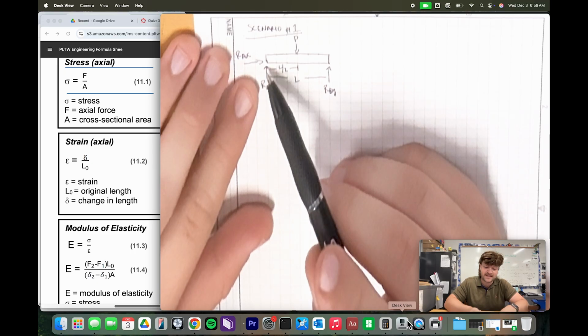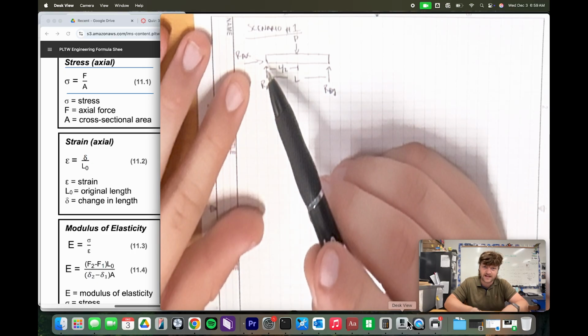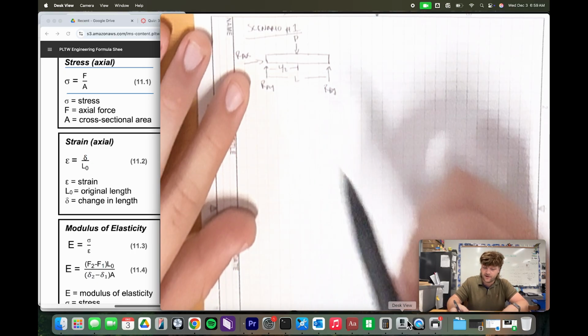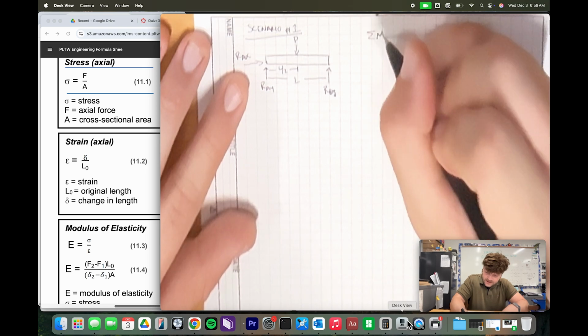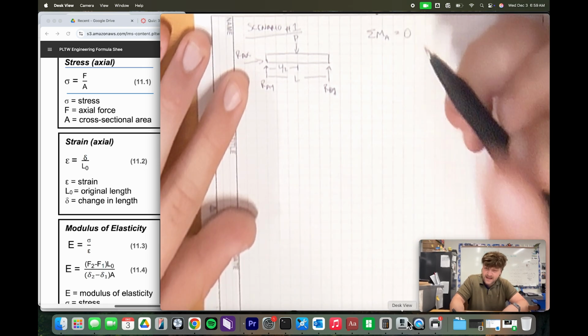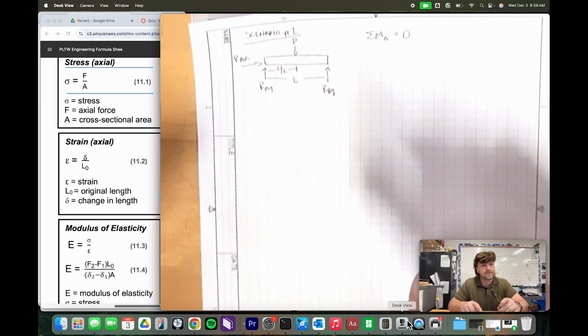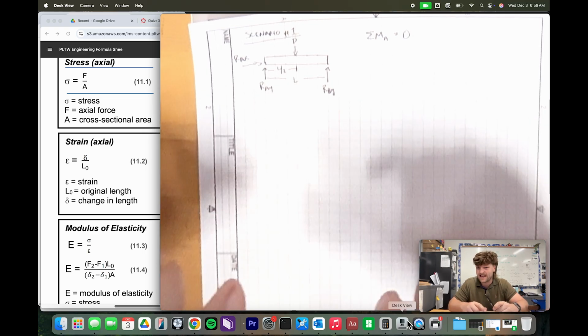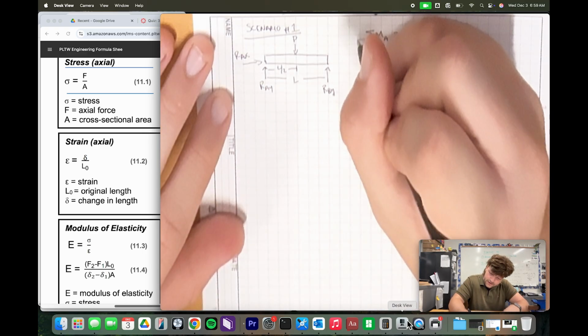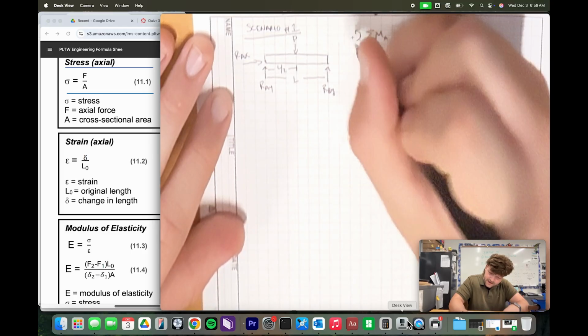So as you can see here, we have RA, the reaction force at A, and that actually has 2 unknown forces. So if we end up doing that, it's going to help us out. So sum of the moment at A. Now remember, we want to ensure that clockwise rotation is negative, so counterclockwise is positive. That's a standard convention, right?